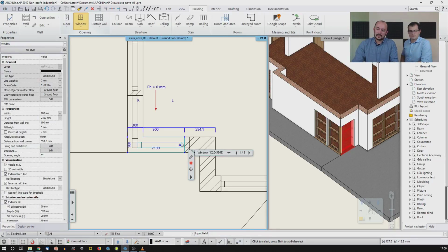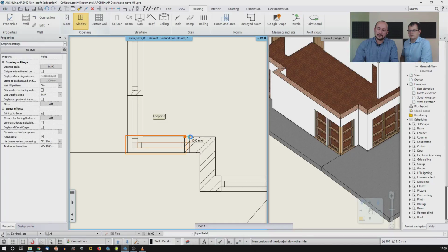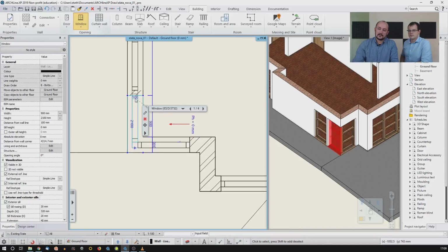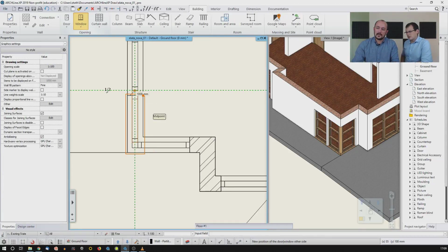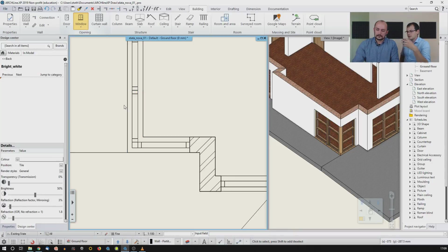So in this case, you need to click on them and click on the corner points and change the size, for example. The same thing you can do on the other side. You can select the window, click on the endpoint, change size, match it with the other one. You could also be typing in the values, right? Yeah, you could, but in this case, because we see the drawing, it's simply easier, because we don't know the distance; we are processing an existing drawing.